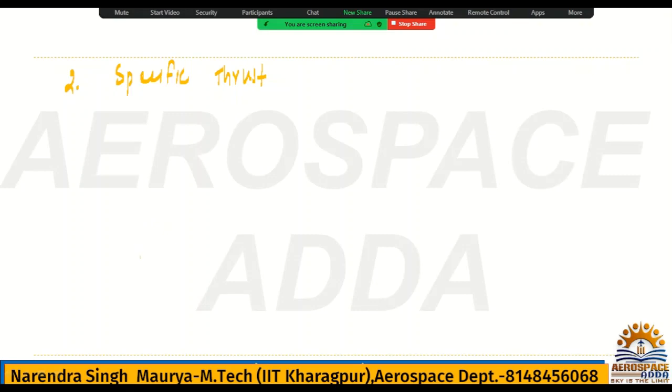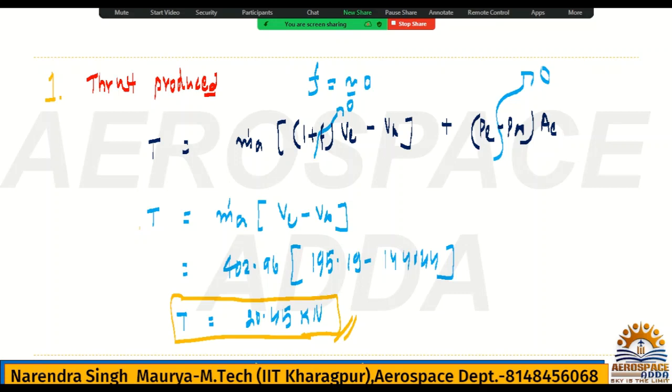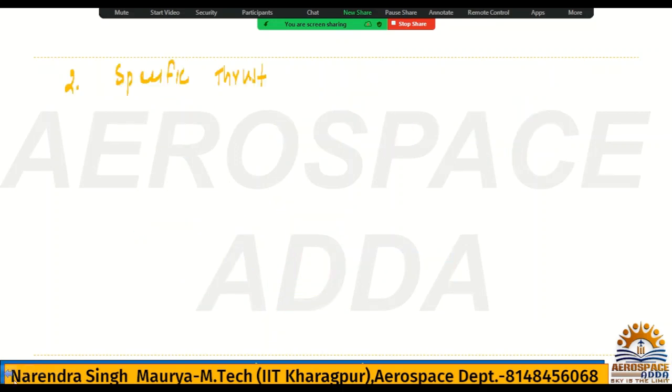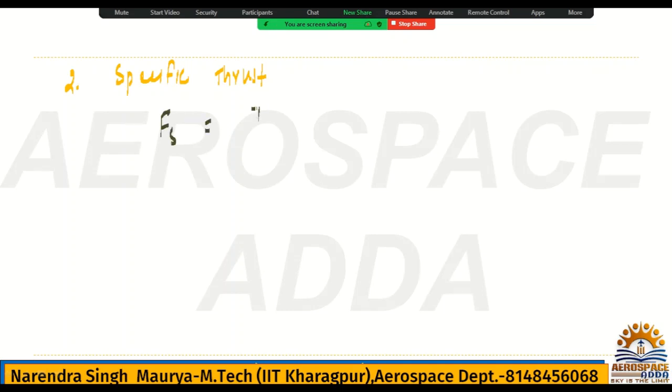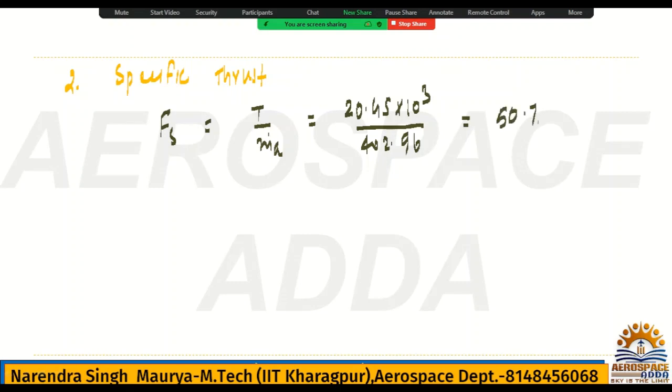Next, here thrust you had seen 20.45 kilonewtons. This is the thrust. What is the specific thrust? Simple. Specific thrust Fs is nothing but thrust divided by mass flow rate of the air. Thrust you had calculated 20.45 into 10 power 3 divided by the mass flow rate, 402.96. If you do this, you will get 50.75 Newton second per kg. So this is the Fs, which is nothing but specific thrust.